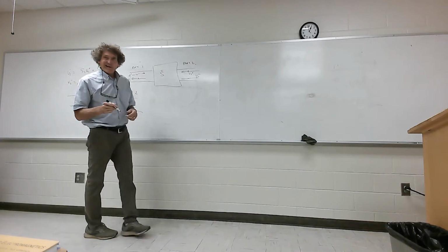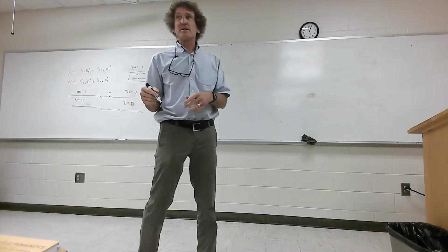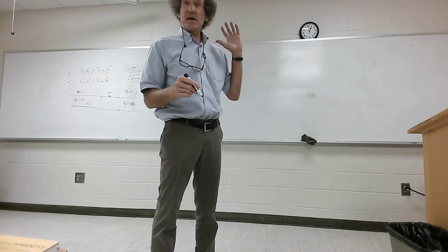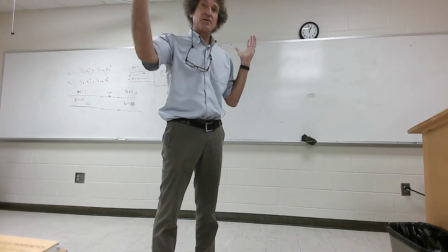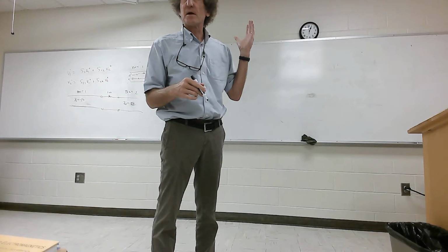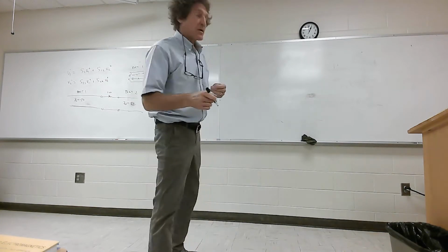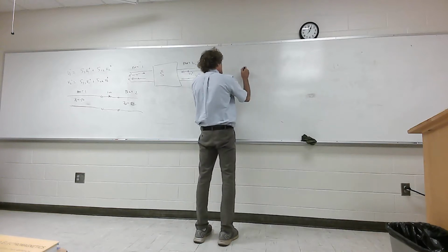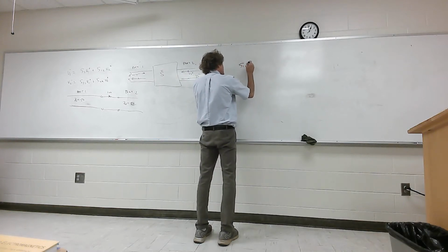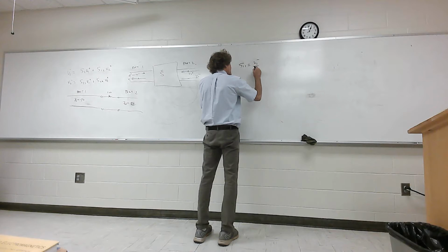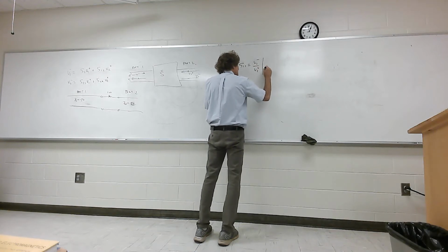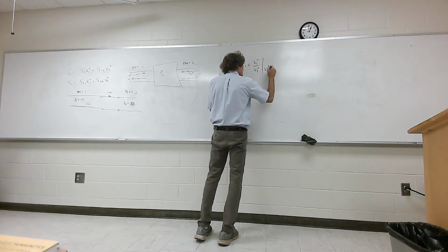How many remember, at least to get these things, there are reflection coefficients with matching loads on the other side, so there's no reflections. And then there are transmission coefficients, correct, class? So what I always tell people to do when you do these, first, you realize that S11 is V1 minus over V1 plus, assuming V2 plus is 0.